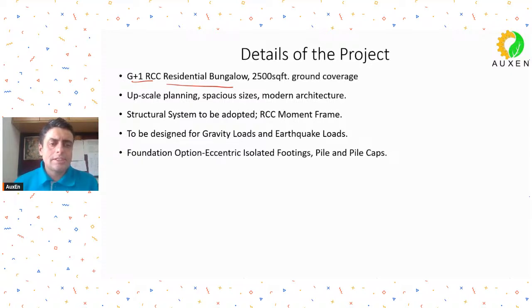So the structural system that we will adopt will be an RCC moment frame, and we will design our bungalow for gravity loads and earthquake loads. The foundation options that we will use will be isolated footings and eccentric footing, and as an additional scenario, we will also be designing the piles and pile caps.